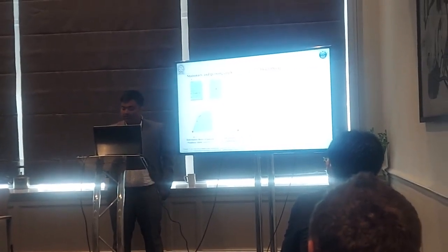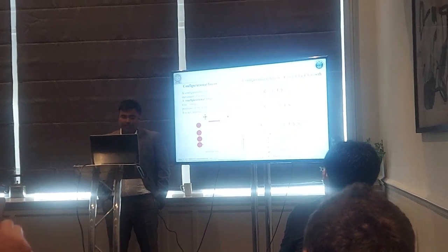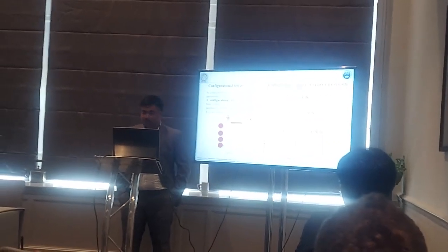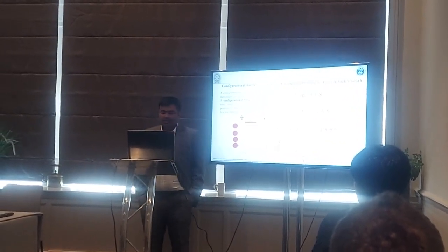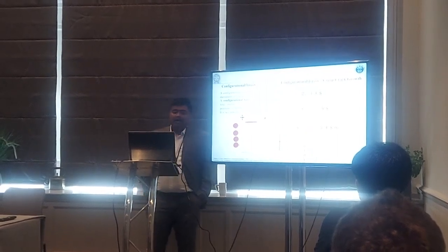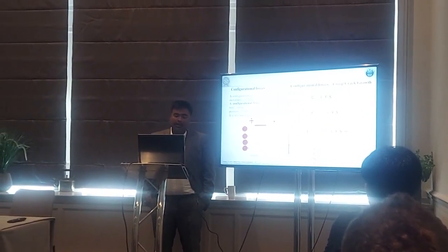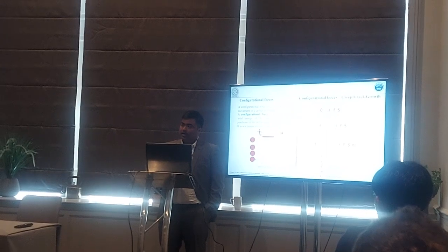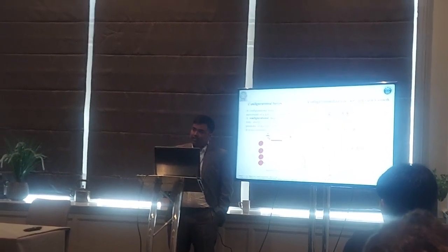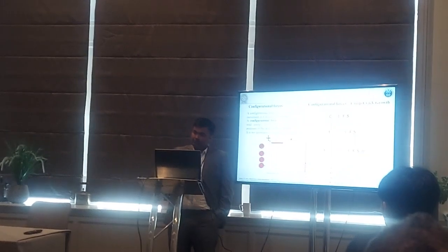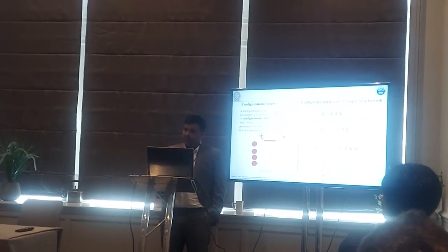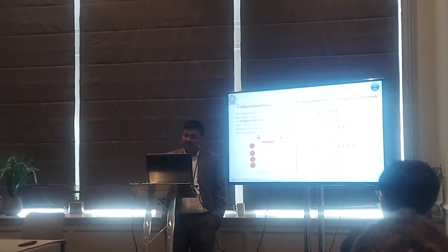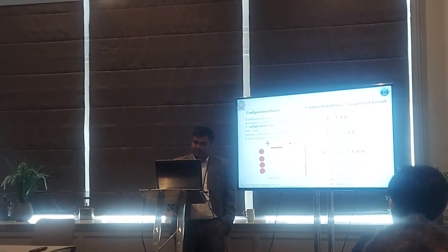To solve these problems, the new concept recently used by Kolednik in the area of fracture mechanics is configurational forces. The concept of configurational forces is not very tough, it's very easy, and this is the driving force. Suppose this is an interstitial atom sitting on an octahedral or tetrahedral site, and the surrounding atoms are bigger, producing some compression here, but another atom near the surface has lesser compression because the free surface is there.